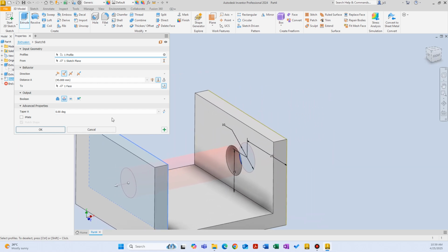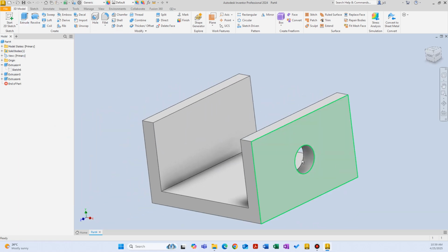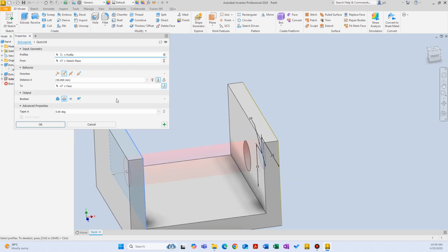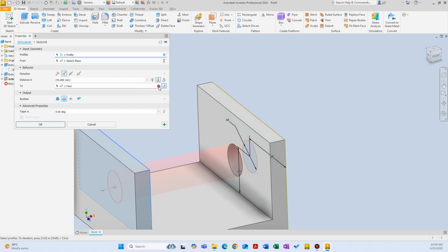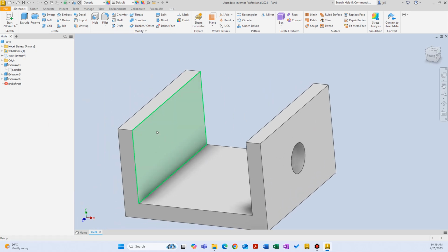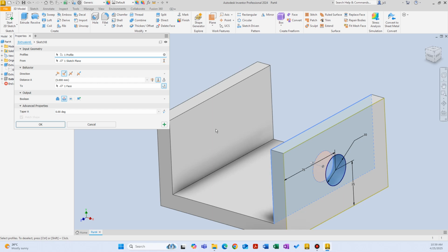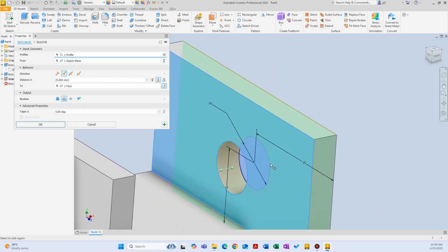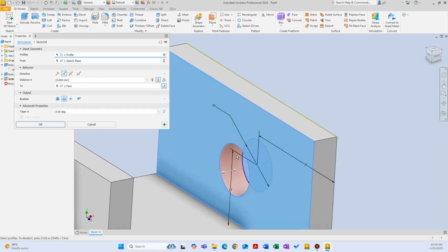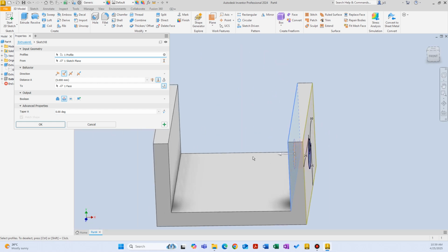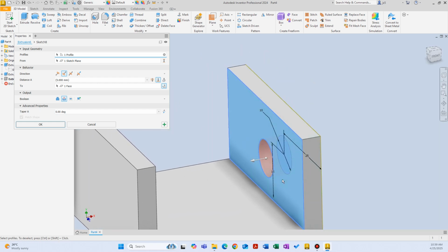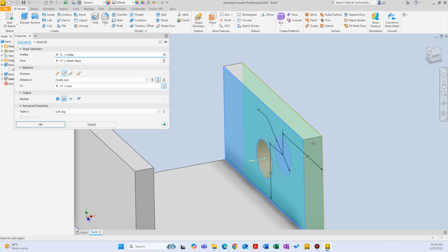Right now, for example, it's only cutting that wall. If I clear that selection and select this face, the design doesn't change. But actually, the way I'm cutting that hole is different, because I'm cutting everything on its path until it reaches this face, or until it reaches this face. So if I add something in the middle, this option will not touch that because it only cuts everything on this wall.